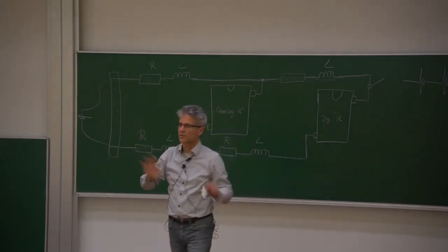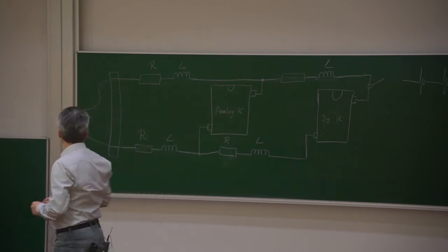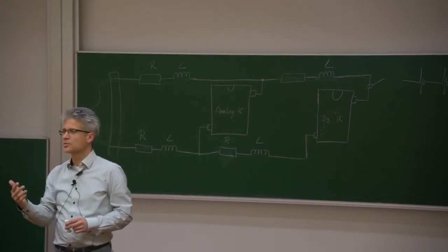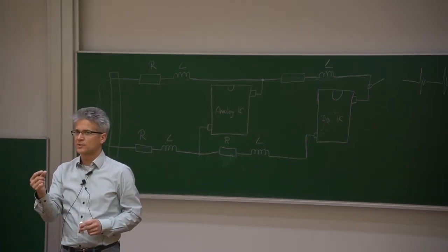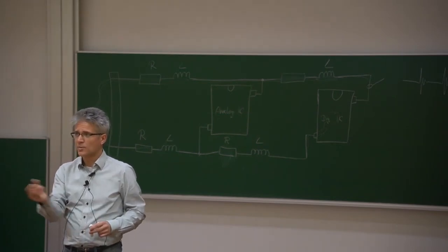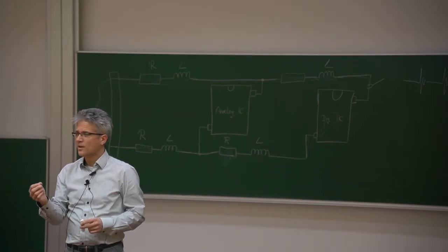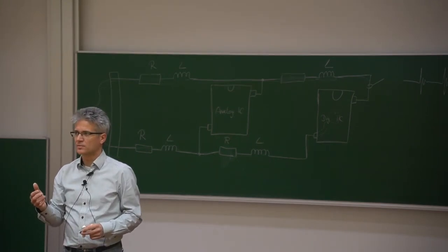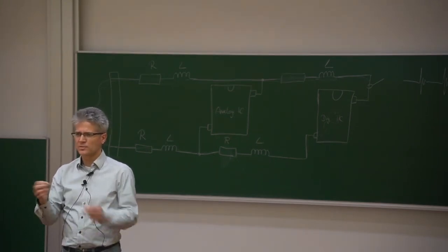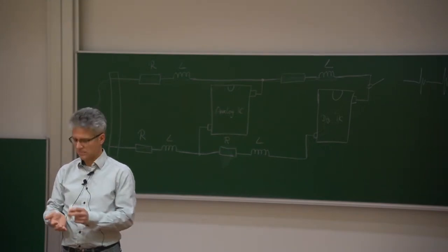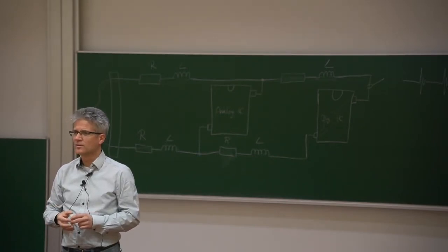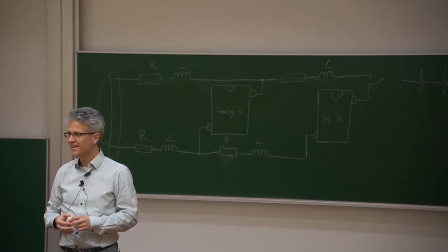In reality, there are stray capacitances. The thing is, what I think is that very often we get the impression when reading textbooks that there is a certain inductance of a printed circuit board trace. Or maybe you've already heard something like a 1 millimeter bond wire has an inductance of 7 nanohenry or something. Have you ever heard of this? That a piece of bond wire has a certain inductance? Or a printed circuit board trace, 1 centimeter is 7 nanohenry or something? It's interesting because actually it's completely stupid.